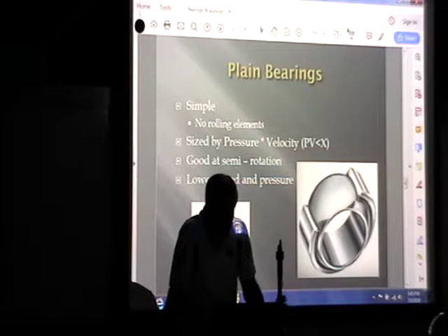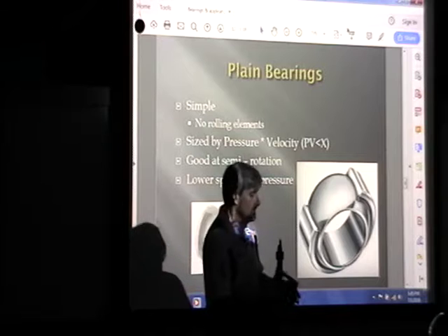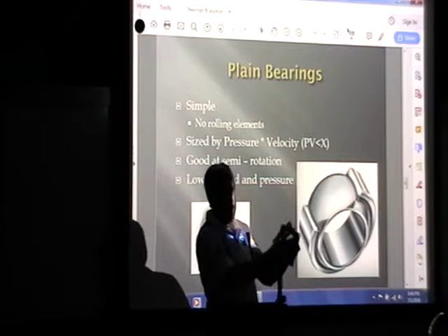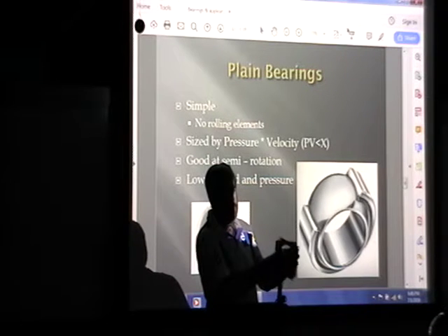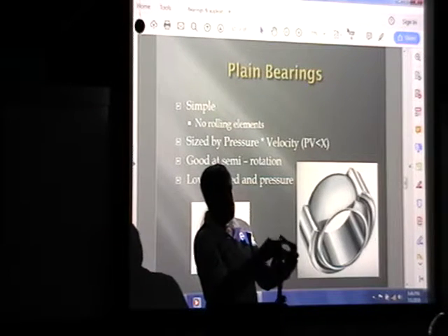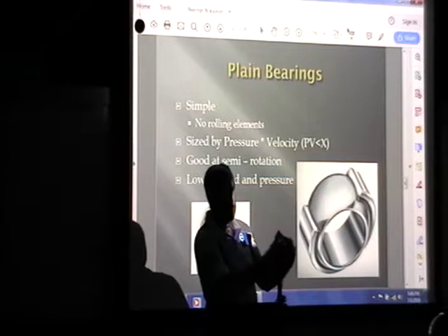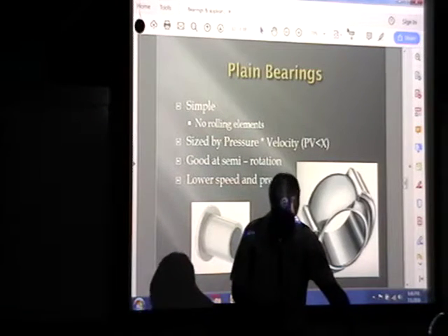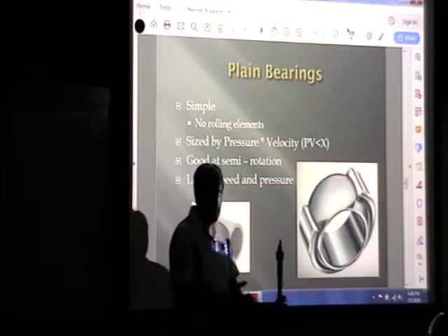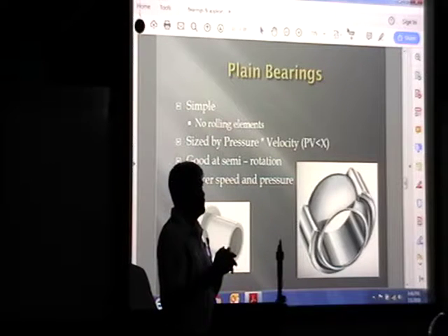They are really good at a lot of things. Mostly in cases where you're not getting a full rotation on a mechanism. For instance, if I'm only doing quarter rotations like this, if this was a radial bearing, that would be a good instance for a plain bearing because the balls are not getting full rotation within their cavity. It would be a bushing, just getting brought back and forth. That's where those bushings excel. If you're going really low speed on a full revolution, there's some use for plain bearings. I think the Raptors used a plain bearing on their in-feed systems because there wasn't a lot of load there.